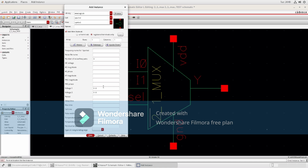Close. Now from here we have to give some values, and the values are voltage 1 is 0, voltage 2 is 1 volt, and the rise time should be 100 nano, 10 nano.